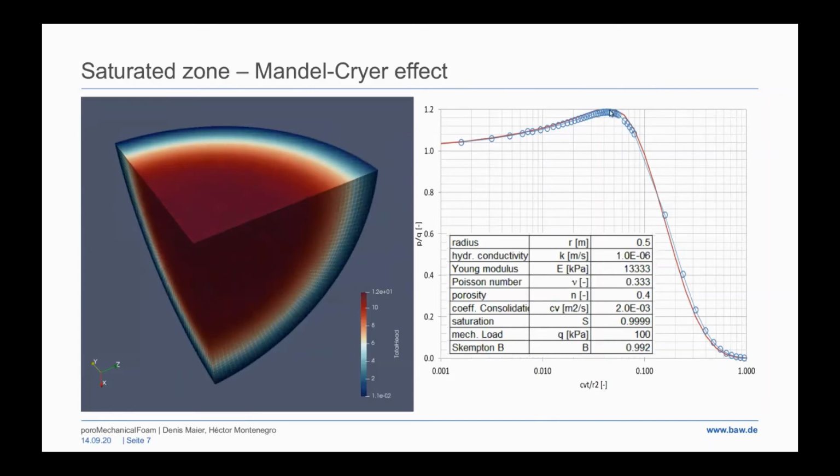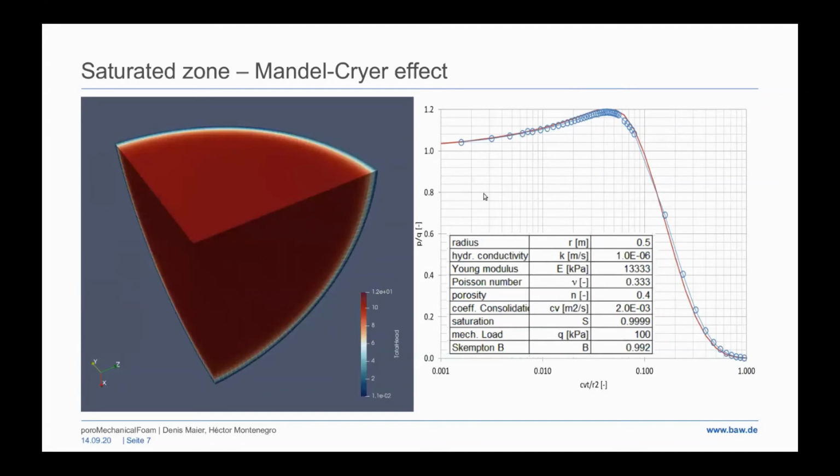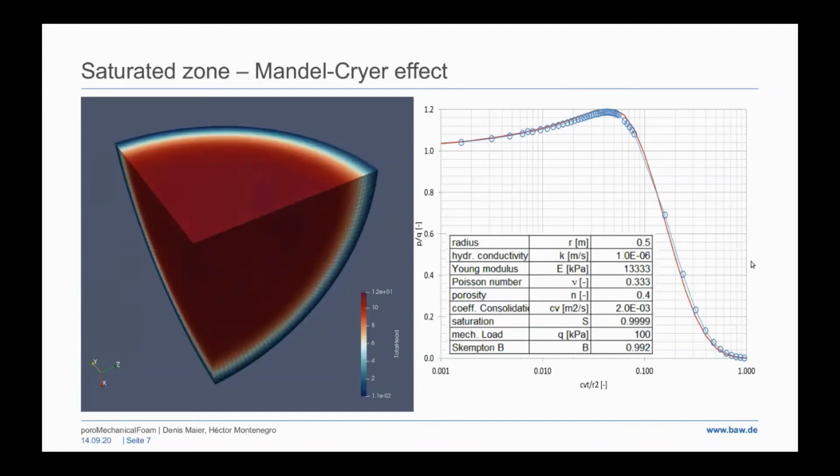And after you hit that maximum, you start to have a rapid drawdown of the pore pressure, because the water finally finds its way out of the ball completely. So we have the analytic solution and the solution of the calculations, and they agree quite well. So we're really confident that we have the coupling right.